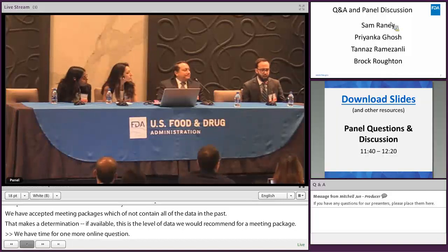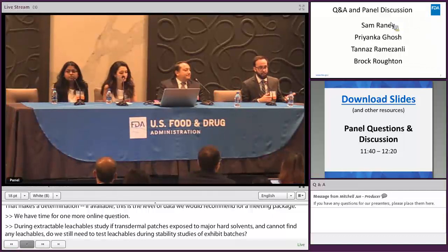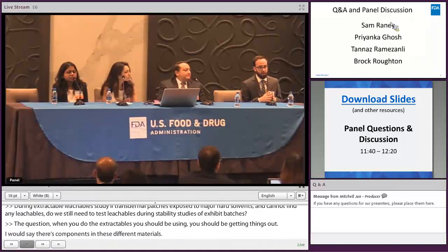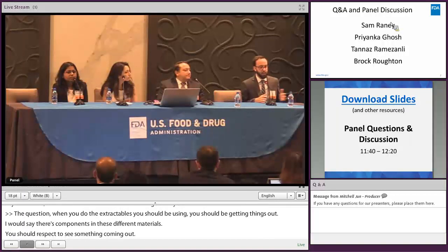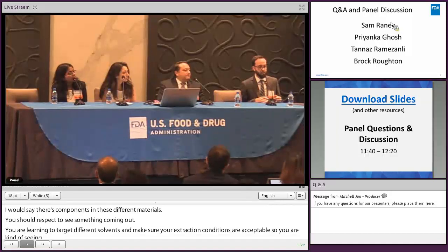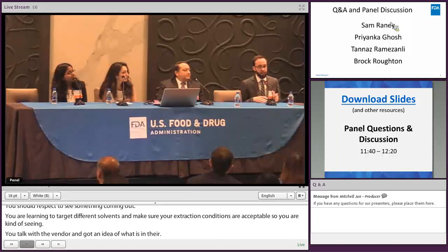Thanks for the question. When you're doing the extractables, you should be getting things out. There are components in these different polymeric materials, so you should expect to see something coming out. So again, you want to target different solvents, and then make sure your extraction conditions are acceptable, so that you are seeing something. And then you've also talked with your vendor and got an idea of what's in there. So let's say you did the harshest extraction possible, you're not seeing anything, we would still expect to see a leachable study also provided.